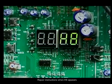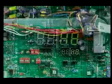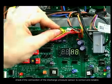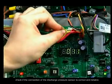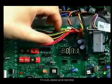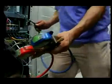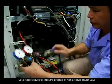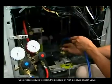Repair instructions when H8 appears. Step 1. Check if the connection of the discharge pressure sensor is correct and reliable. If it is okay, please go to the next step. Step 2. Use a pressure gauge to check the pressure of the high pressure shutoff valve.